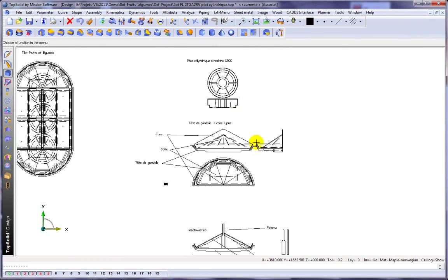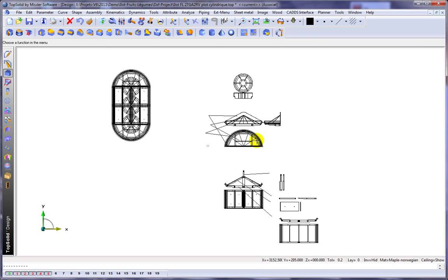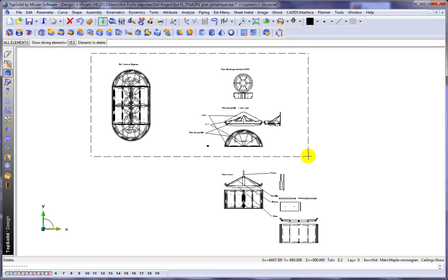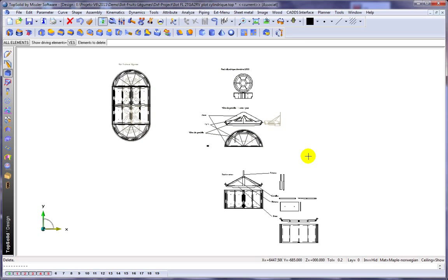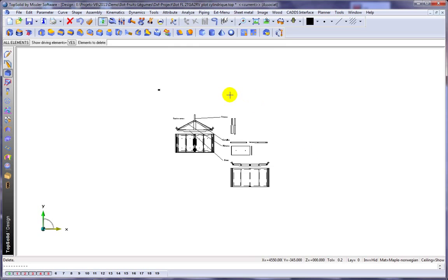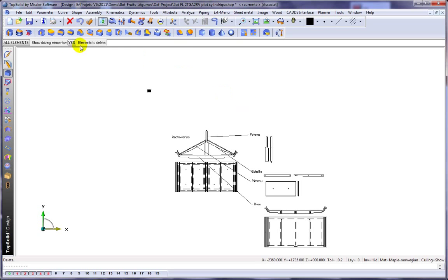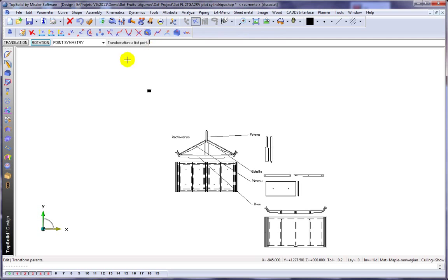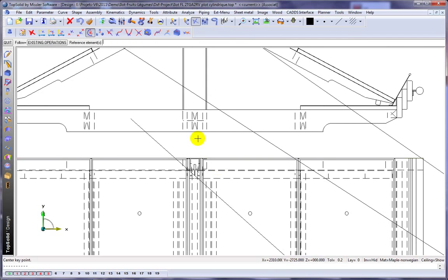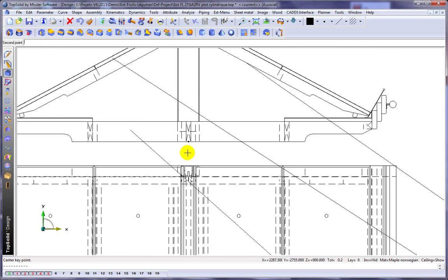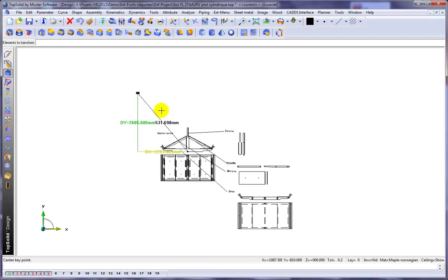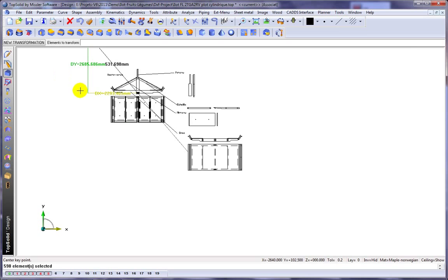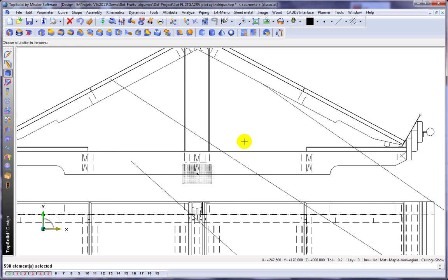We have plan views and we have some side views, and basically what we want to decide is which of this data is the data we want to work in. We're going to get rid of all that up there and focus on the section down below. To begin with, we're going to transform this data and just move it over to our 0 point, and you'll see why in a little bit. This will make modeling a little bit simpler. So here we'll go ahead and say move from the center of that to 0, grab everything, and we're done.